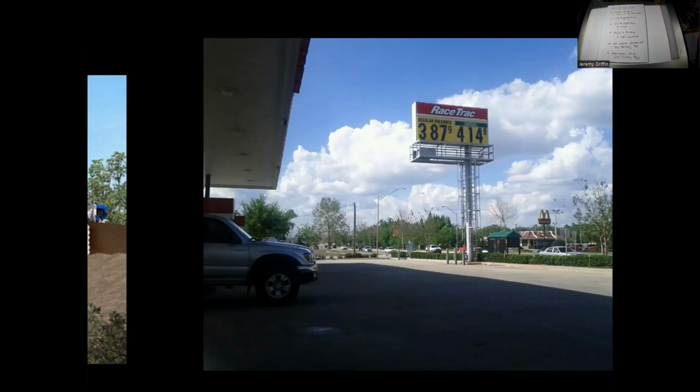Oh, you've actually worked with this. All right. So yeah, a good rule of thumb. Again, we're looking for a minimum case for cost reasons, right? It costs to drill. It costs to elongate the pole. A good rule of thumb is a third of the height of the pole. So if this pole is 100 feet tall, say, okay, well, 33 feet, I have to dig down at least that far.